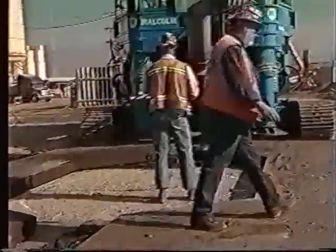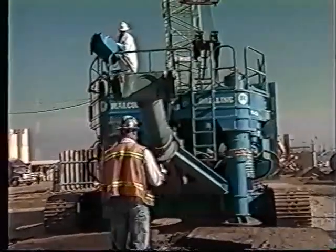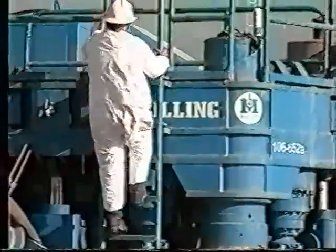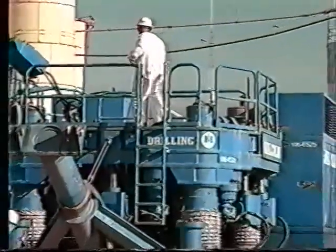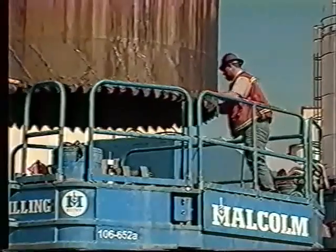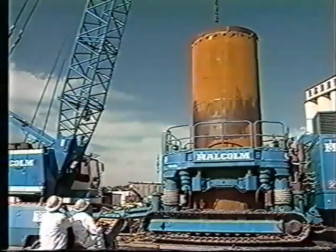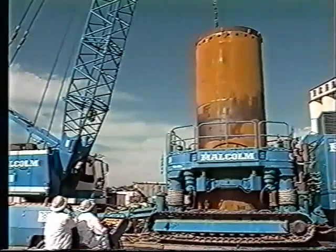The massive rotator, weighing 260,000 pounds, was positioned over each hole on a specially made steel platform. The rotator measures approximately 18.5 feet in width, 22 feet in length, and 13 feet in height. An initial section of casing with cutting teeth to facilitate the coring action was first positioned over the hole. Temporary sections of casing were continuously twisted and pulled steadily down into the ground.